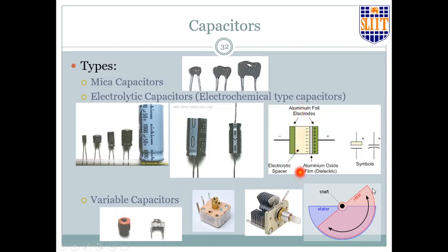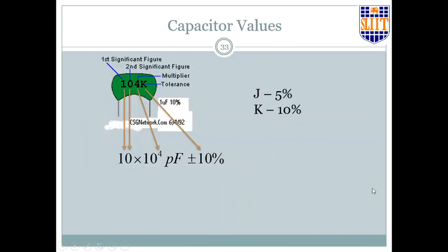The electrolytic capacitor, the oxide layer is very thin and the dielectric is actually conductive. Salt solutions are conductive, right? So you can treat the other side of the oxide layer as the second metal plate, not the actual physical plate, right? So that is why the D becomes very small. So all this stuff can be considered as conductive. So this surface becomes the other plate, right? Okay.